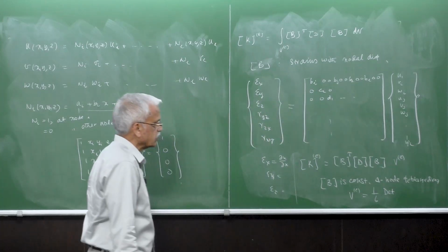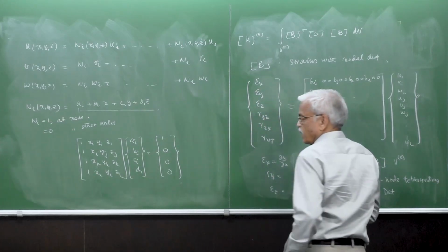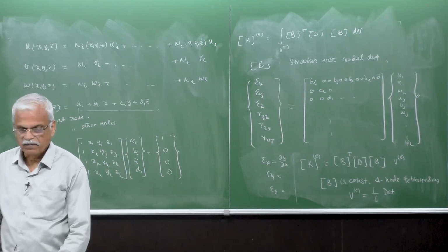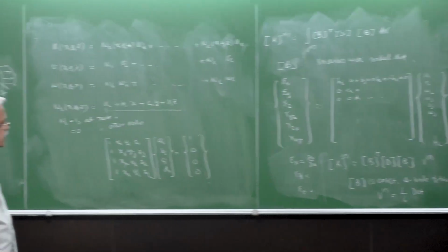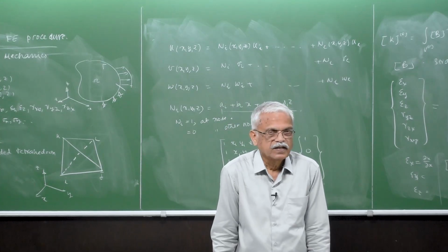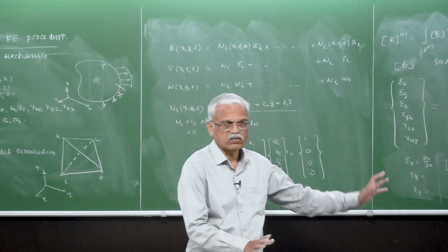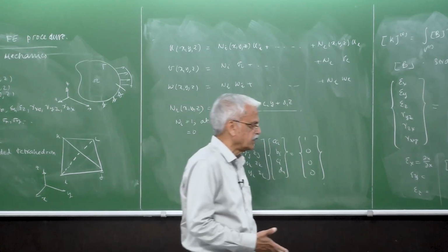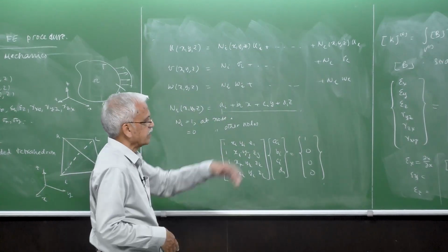Okay, so like this, we have the K matrix defined. Similarly, just like in 2D, we also have the contribution from the body forces. This is how we can extend our 2D concept of solid mechanics to 3D solid mechanics. It's just 1 degree of freedom more than the two-dimensional analysis, and the rest of it follows exactly the same steps.